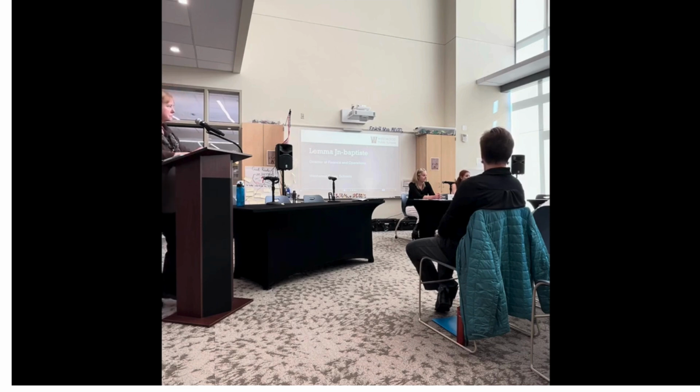That was nerve-wracking. And we were faced with a unique challenge in that there was a winter storm on December 18th that took the power out. And this happened 8 weeks before move-in day. When that storm happened, we got a phase imbalance message on the system, on the tandem chiller systems that those of you who were in the mechanical room saw. So all 6 condensers and the 12 compressors in that phase imbalance were damaged. And we understood very quickly that they had to be completely replaced.